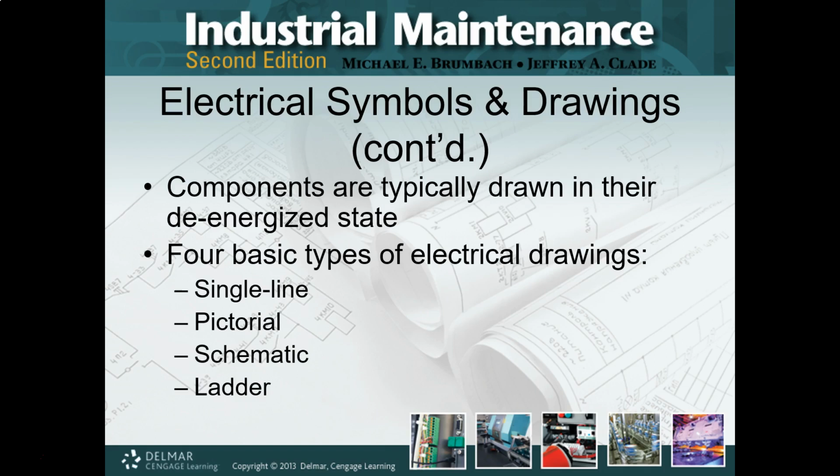Where does this really become important? Relays and switches. That's the biggest one, relays and switches. So you'll have to remember that when things are energized, relays and switches change their state, and then different things happen. And depending on what drawing you use, you can see what goes on. So single line drawings, pictorials, schematics, and ladder.